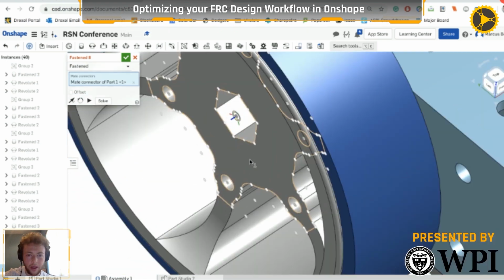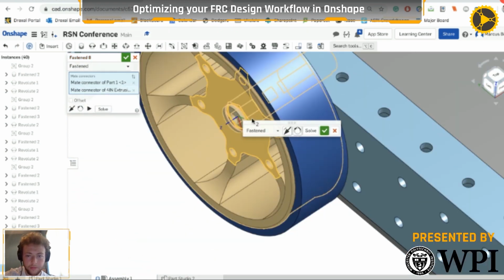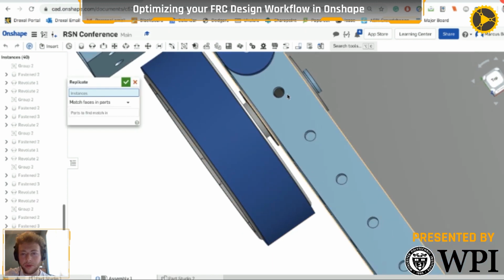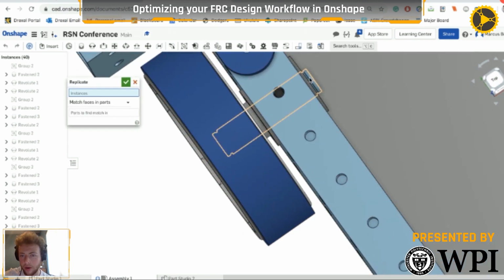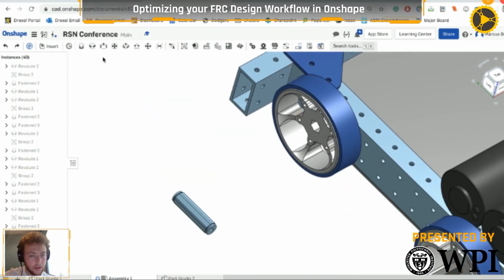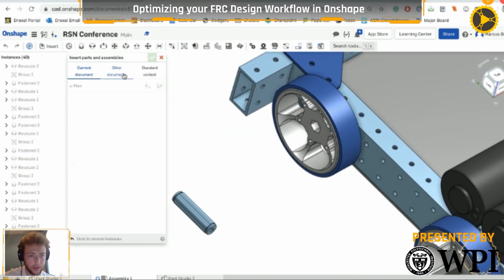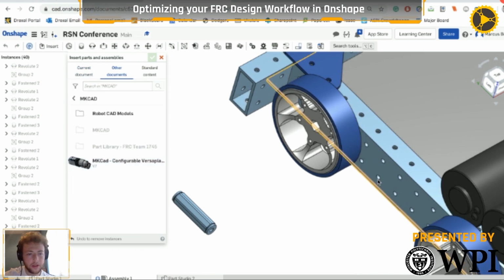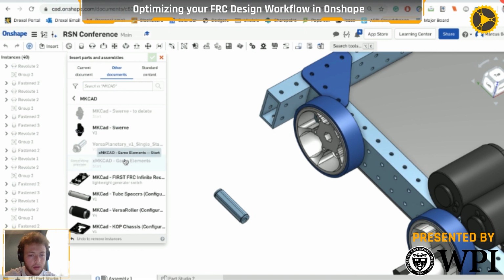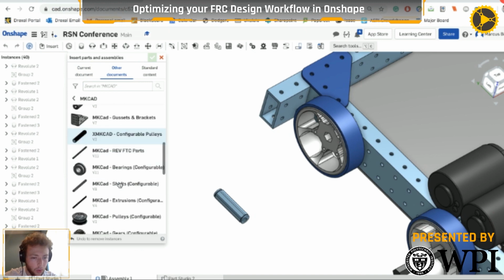So I'm going to go ahead and make that in there. I will use the replicate tool again just to make our lives easier a little bit. You'll notice if I pan over to the other side or rotate over, that's exactly right. That's where I want it to be. I actually should have done the snap ring on this shaft so we don't have to put it all in again. One of these days I will go back into that feature and put the snap ring and the retaining and the bolt actually in there.